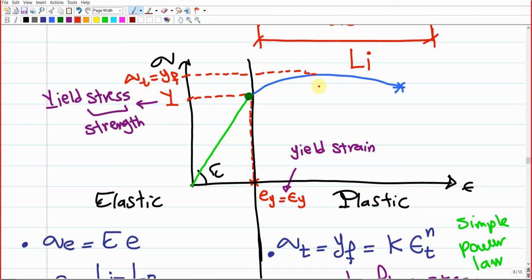So we shall end up with a certain deformation of the material. This deformation, as we agreed, when we remove the load, we're going to return back parallel to the elastic region because of the spring back effect, as we discussed in the previous meeting. So this is a stress level and this is the yield strength.